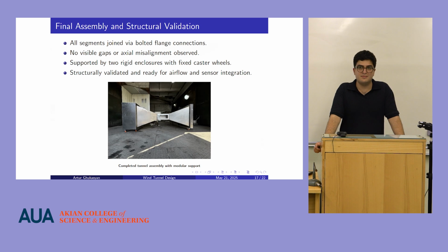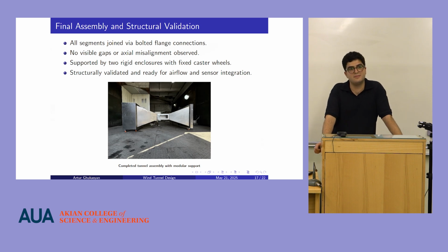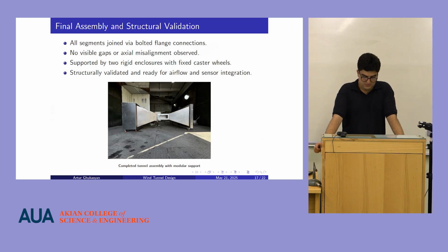A slightly better tunnel. And I think it's worth the effort, because right now, even though a lot of people are putting tunnels together, literally, I wouldn't trust any of those tunnels to have the type of flow which is necessary to calculate flows over UAVs, wings, and so on. It'll be very nice to produce color pictures and photographs, but if we're really going to design something using this, with a little bit of tweaking, I truly believe we can get there. It just requires some thought about how long the test section has to be, but it's not that difficult.